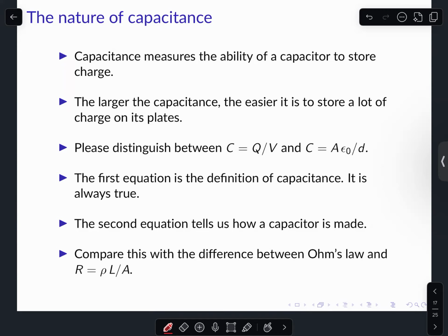So, what the hell is capacitance? What's it mean? What's it taste like? Capacitance is not quite the capacity of a capacitor. Our simple model for a capacitor is that you could store an infinite amount of charge in them. But capacitance is how easy it is to store some amount of charge. Capacitance reflects how much charge you can store on the capacitor for 1 unit of voltage to develop across them. Why is this useful?